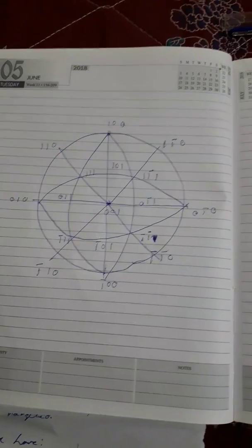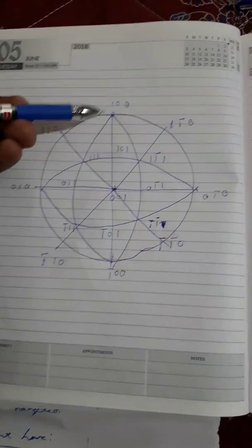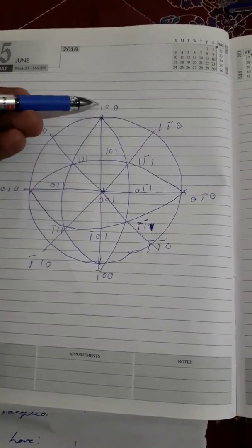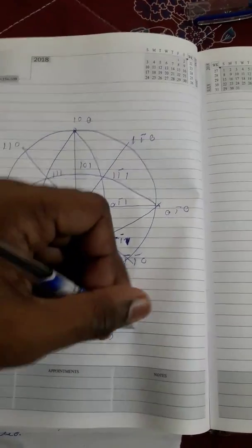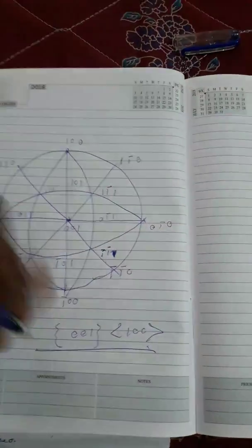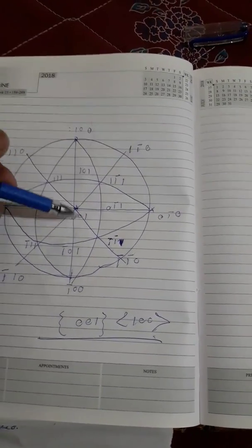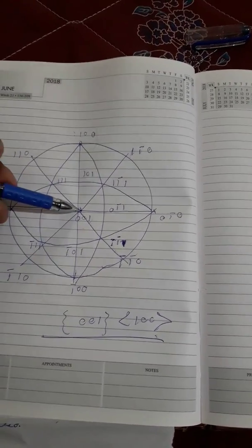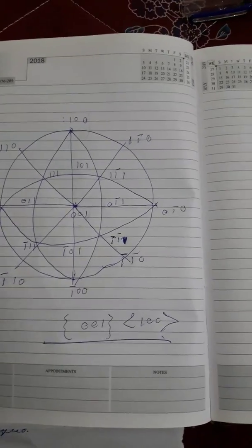So what we can do now is, we already have our orientation. This is basically nothing but the 001 <110> orientation, because 100 lies parallel to the RD, and 001 lies parallel to the ND. Now the question that arises is, how do we construct the 100, 110 and 111 pole figures? To do that, the next step would be as follows.